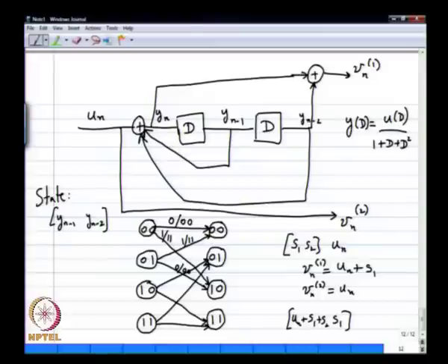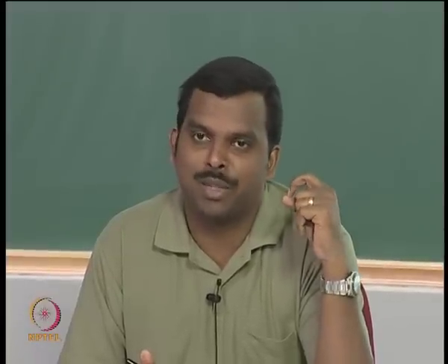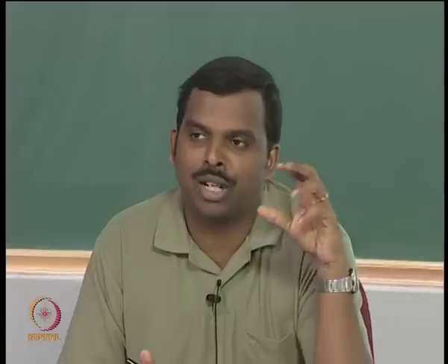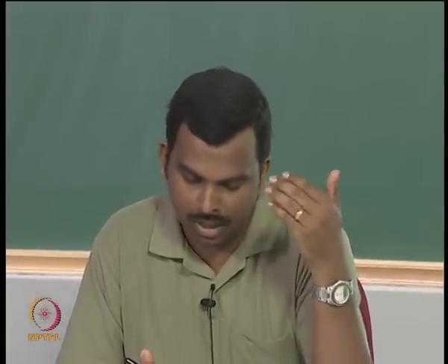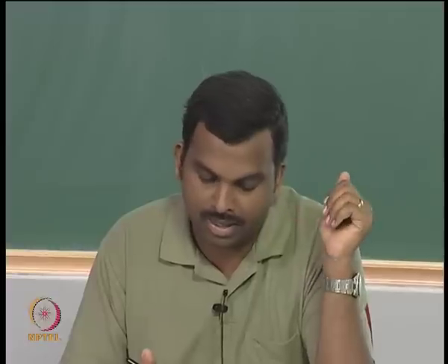It will have 2 outputs from each state and 2 inputs into each state. I think in any trellis that will be true, okay. So you have to have these things, and you find the output for one branch, you can find the outputs for every other branch pretty much, okay. It is just a question of figuring out the inputs and everything will work out very fast, okay. All these things are checks you can use, like I said, in an exam situation.